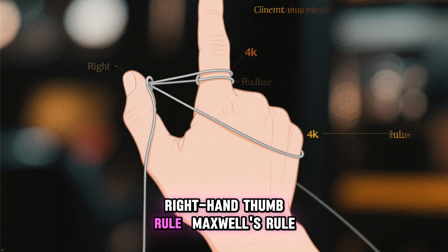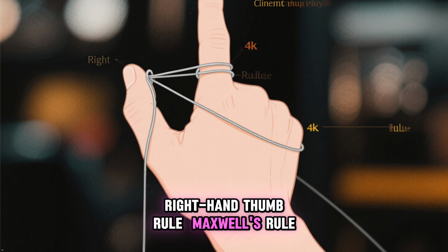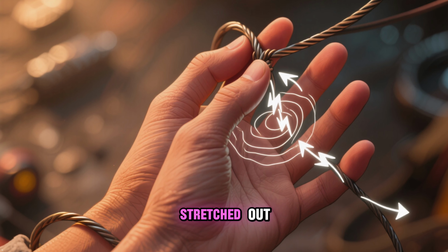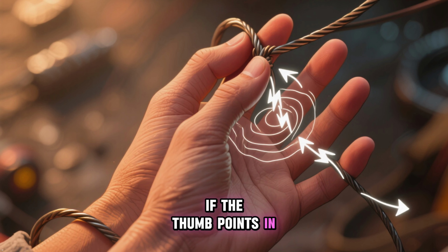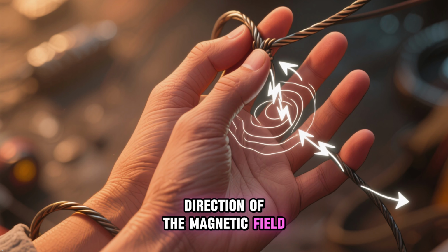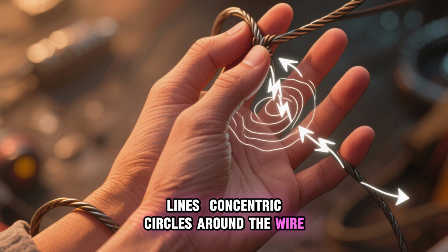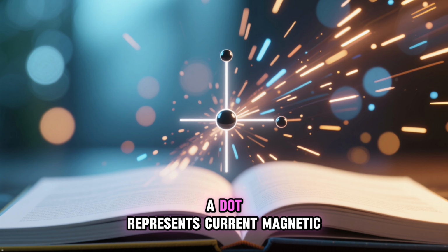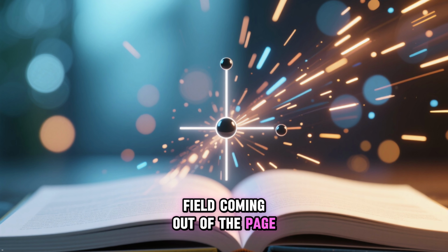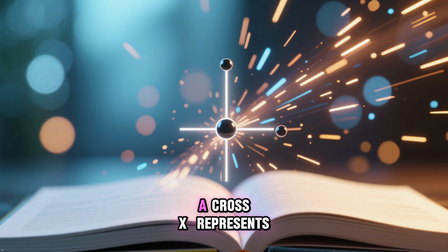Right-hand thumb rule, also called Maxwell's rule. This rule determines the direction of the magnetic field around a straight current-carrying conductor. Rule: imagine holding the conductor in your right hand with the thumb stretched out. If the thumb points in the direction of the current, the curled fingers show the direction of the magnetic field lines, concentric circles around the wire. Convention: a dot represents the magnetic field coming out of the page. A cross represents the magnetic field going into the page.